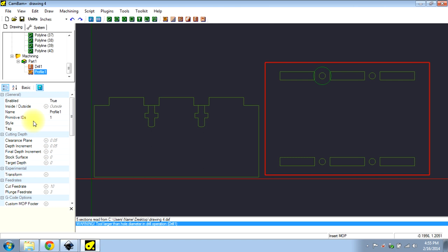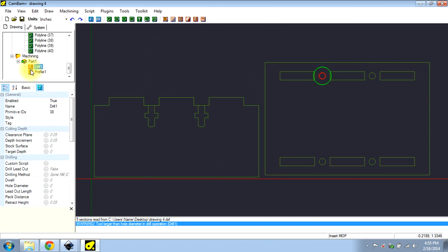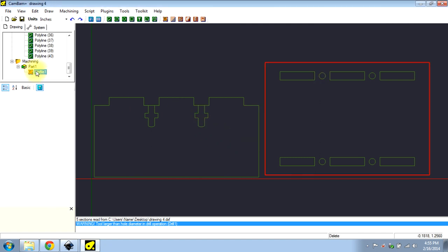Click the outside of something. I want you to profile it. I want you to cut on the outside of the line. It's 3/4 of an inch thick, you know, 0.75 inches thick. I want you to cut 0.752. I want you to cut on the outside of the line. I want you to add tabs, which are little pieces left uncut so it doesn't fall out. All of that is done here.